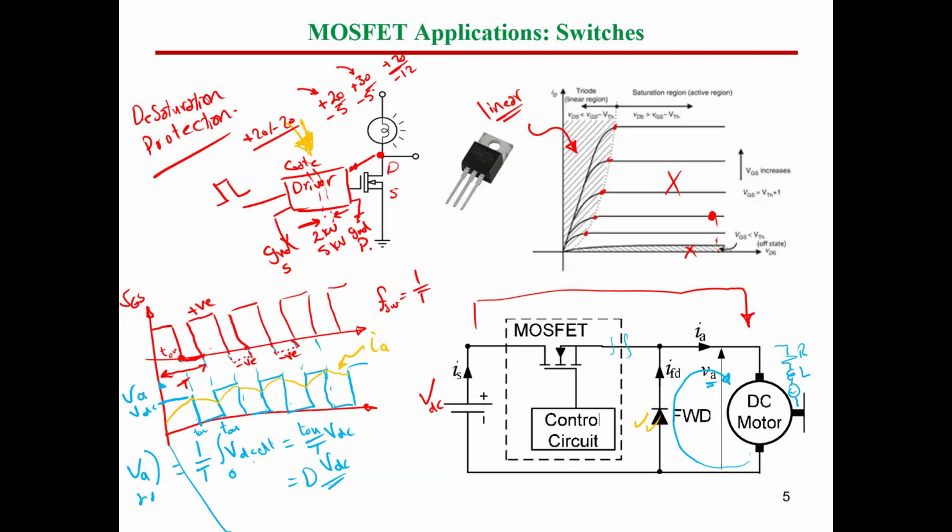So we prefer, especially in power applications, to increase the positive gate voltage to reach the maximum current capability of our MOSFET that we need in our application, and at the same time to apply a negative voltage to the MOSFET to be sure that it has been completely turned off.